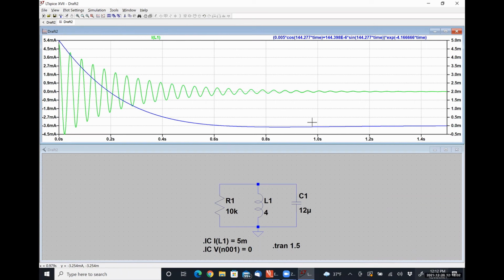Okay, so it is absolutely imperative that you take into account LT Spice works in linear frequency and our analysis is in angular frequency, and you need to do a conversion there, okay? So you must convert omega D to degrees per second by multiplying by a conversion factor of 180 over pi, or you can be doing everything correctly and your simulation will tell you you're doing it wrong, okay?